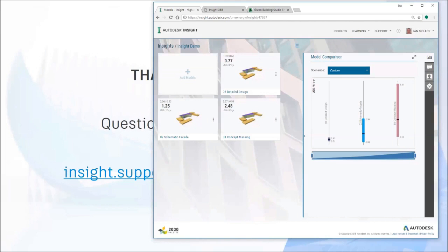And then finally, there is a sort of a fringe case where you can have two walls that are directly connected or adjacent, but not quite parallel. And that's a little limitation we have at the moment. We call it non-parallel sandwiches, where it won't create a wall. And what you should do there is pick one of the walls and set them to non-room bounding, leaving just one wall. That's something we plan to fix.